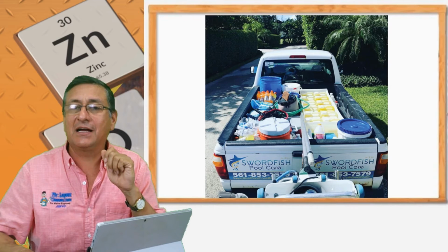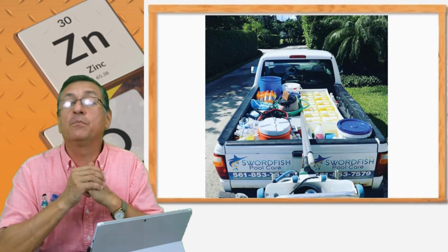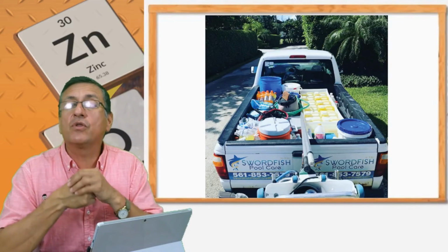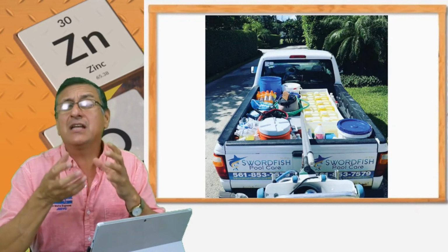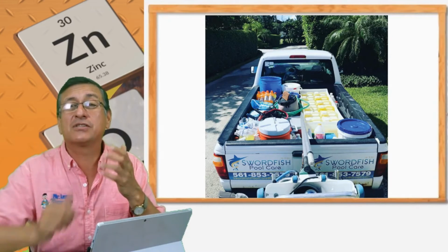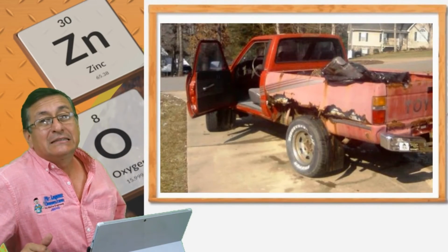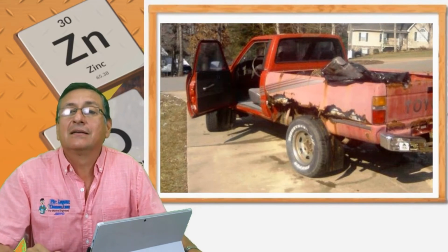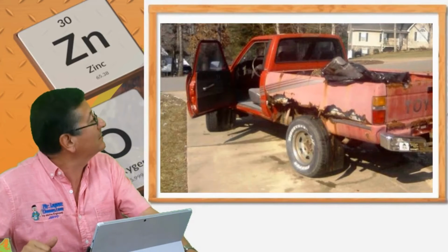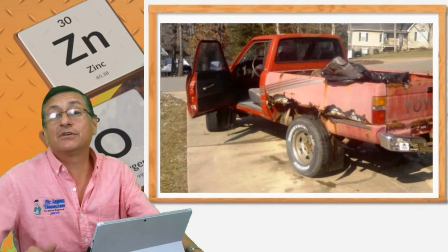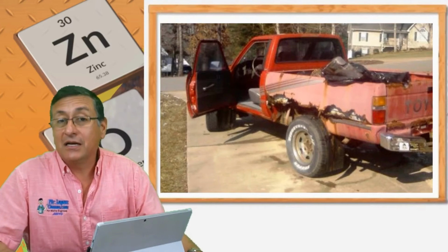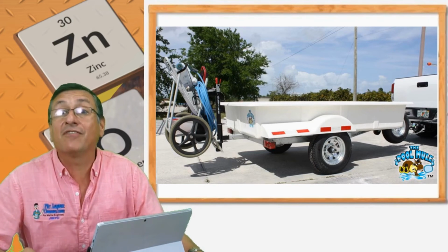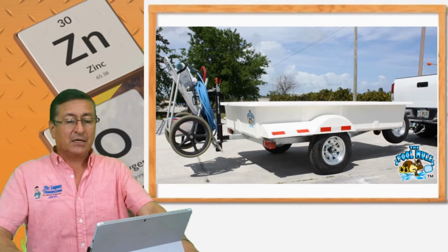You remember the guys dedicated to the service of pools, they use a lot of chlorine to keep the water of the pools clean. The containers with chlorine destroyed the box of the trucks of those guys. That's not good. It produces pitting corrosion, perforates the metal, perforates the steel of the trucks. Yeah, for that reason, if you handle chlorine, you need special trucks with the box in fiberglass or other similar materials.